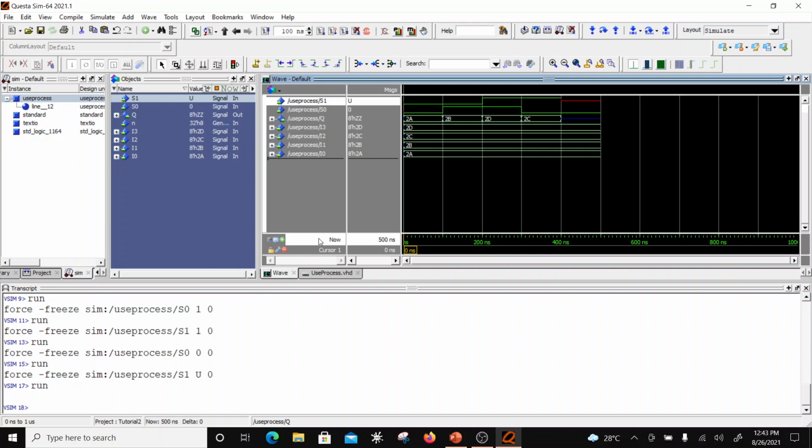And here you cannot have a break statement like in high level languages. You cannot put an exit, okay, because exit, or next, is specifically used with loops. They are not used with branching. Okay, so this you have to keep in mind. So you cannot have an exit statement as a part of the statements in a conditional case statement, right? So let's do a case statement. Okay, so we'll take the same mux example and turn it into a case statement.